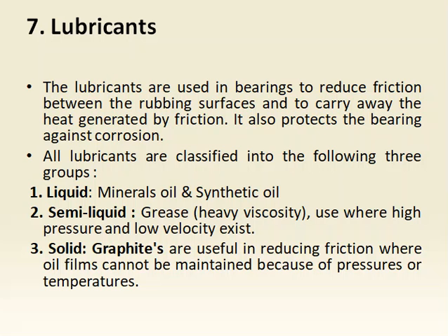Liquids and synthetic oils are generally used where we have hydrodynamic lubrication. Semi-liquids can be used for thin film lubrication, but solid graphite lubricant can be used for zero film lubrication. This is the requirement, and according to the requirement you can choose your lubricant.